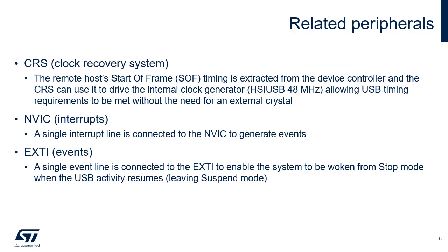Several related peripherals work alongside the USB device controller to manage USB activity in connection with system power modes and software requirements. The clock recovery system eliminates the need for an external crystal by using the integrated HSI USB48 oscillator as the main clock source. Interrupt events are directed to the Nested Vectored Interrupt Controller, or NVIC, through a single line. Additionally, system events, such as resuming from USB suspend mode, can wake the system from stop mode.